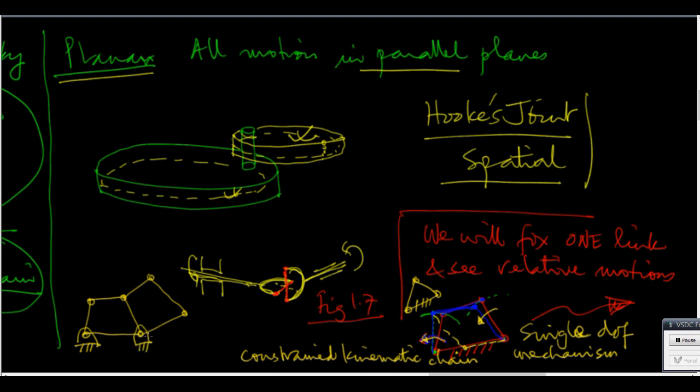And this can be 1, in which case when I move this, the position of this is fixed, and the fact there are those links, the positions of those are also automatically fixed. This whole thing has only 1 degree of freedom. But the minimum number of links you need to have at least 1 degree of freedom is 4. Alright, now we will do kinematic diagrams.